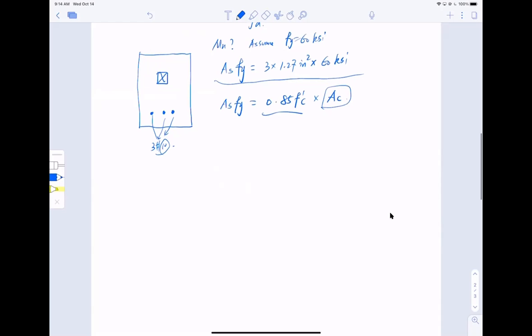So to find it now, I can have 3 different scenarios. 3 scenarios, right? So 3 cases. So case one is, let me use this blue color so I won't be confused. If I call it d, the opening, that would be very confusing. Let me try to use a different symbol since it's the opening. So let's say h_op, right? That's the distance from the top side of concrete to the top side of my opening, right?